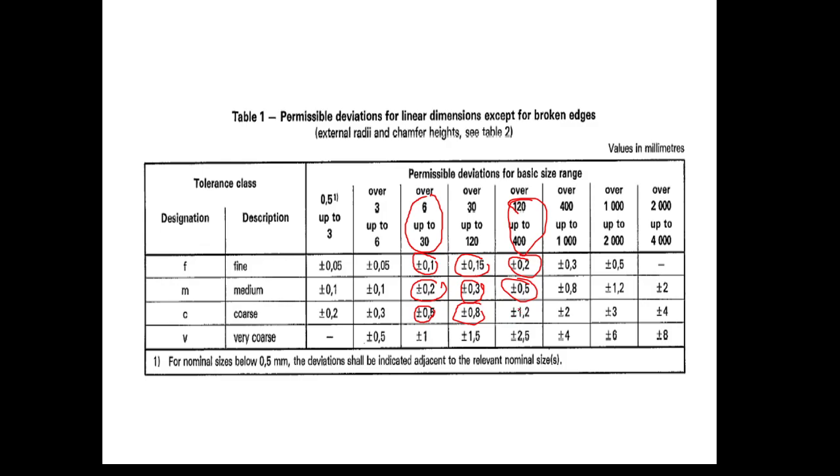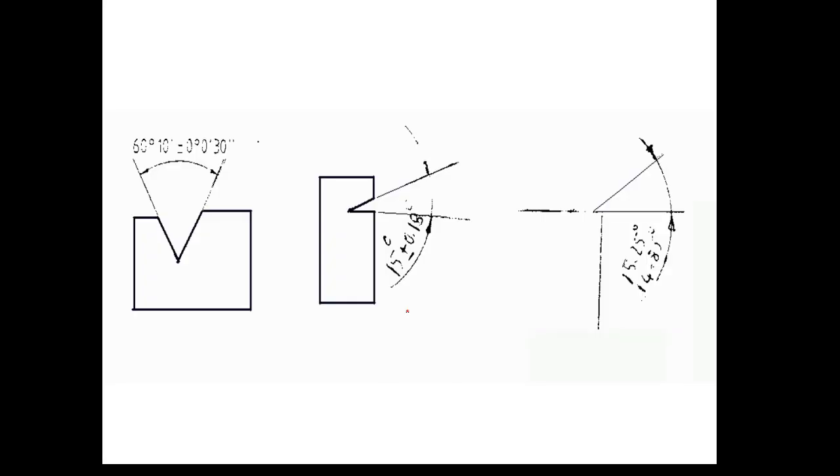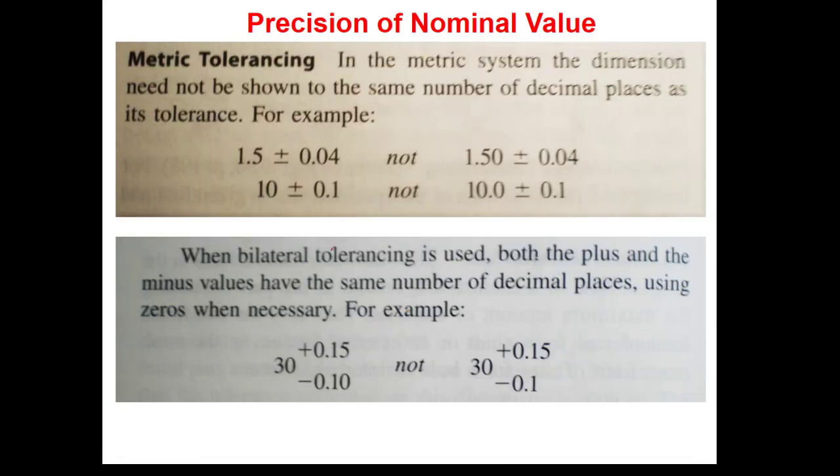Actually it has an integer value. But for the measure of the dimensions, especially non-functional ones, making such a control now ensures that, in accordance with the rule of ISO, since the deviation starts from tenths, the nominal values are to be shown as integers.